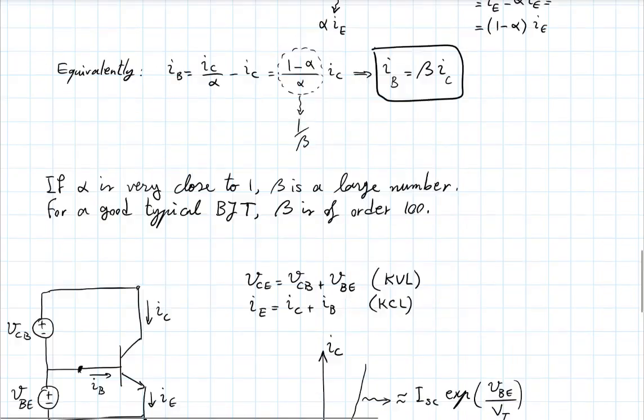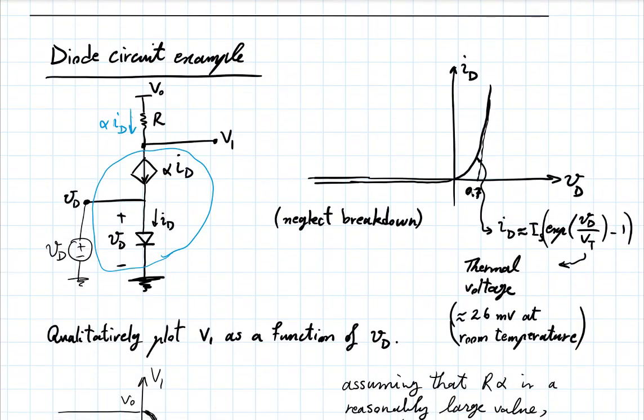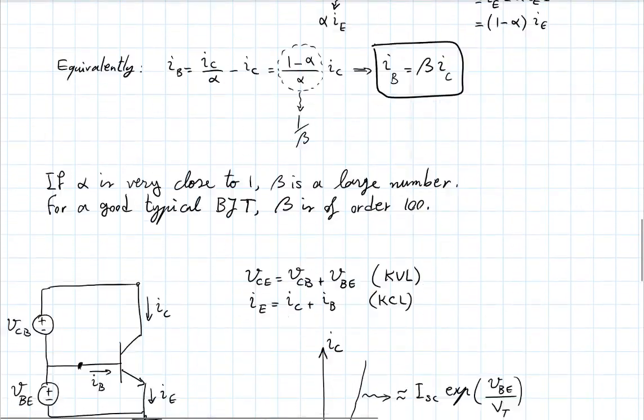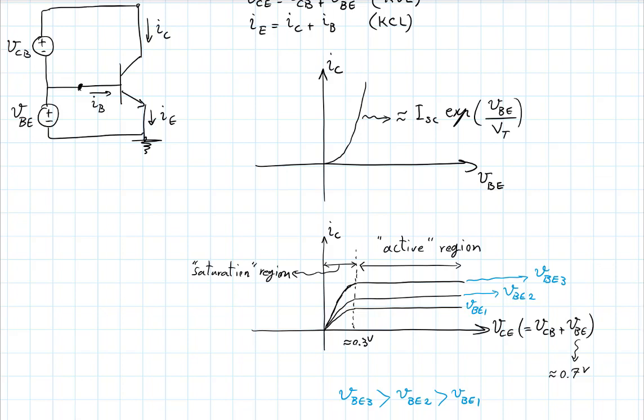Of course, if you had an ideal current source like what we have up here, things are always in active mode, if you want. Even if your V1 is minus 200, right, this would still be in active mode. But in reality here, if your collector voltage drops to a fraction of a volt below the base voltage, the collector current will drop.